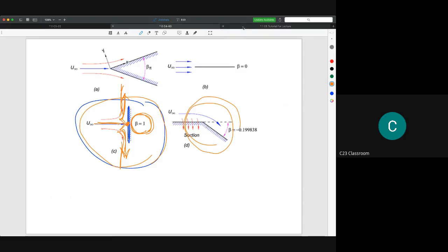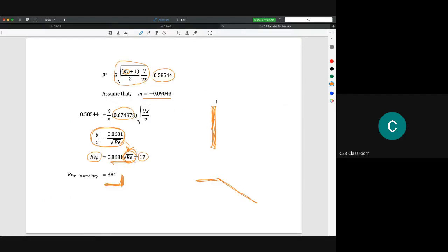So in this situation, whether the flat plate is vertical or given a shape like this, all of these shapes will have their own range of laminar and turbulent boundary layers. It depends on the experiment actually, because this is not a common shape, so you need to verify with experimental work. Okay, so this is the idea of the Reynolds stability.